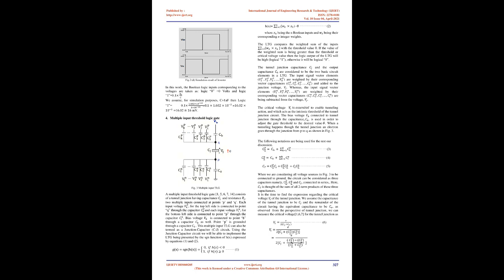A SET [2, 3, 5] is made up of two tunnel junctions 1 and 2 with their capacitances C1 and C2 and their resistances R1 and R2 respectively. Two other capacitors are shown in Fig 1b. They share only a common island bearing a low capacitance.